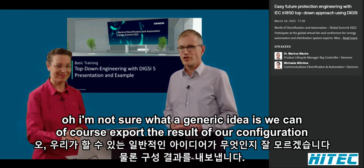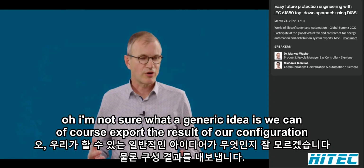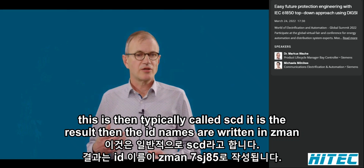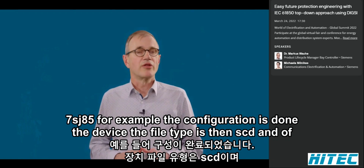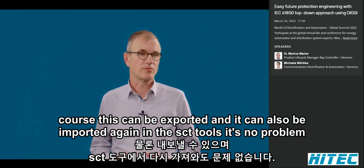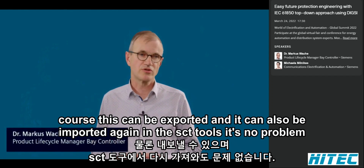And then, does Siemens plan to implement the capability to create SSDs with generic IEDs in DIGSI 5? Oh, I'm not sure what a generic IED is. We can, of course, export the result of our configuration. This is then typically called SCD. It is the result. Then the IED names are written as Siemens 7SJ85, for example. The configuration is done. The file type is then SCD, and of course, this can be exported. And it can also be imported again in the SCT tool. That's no problem.